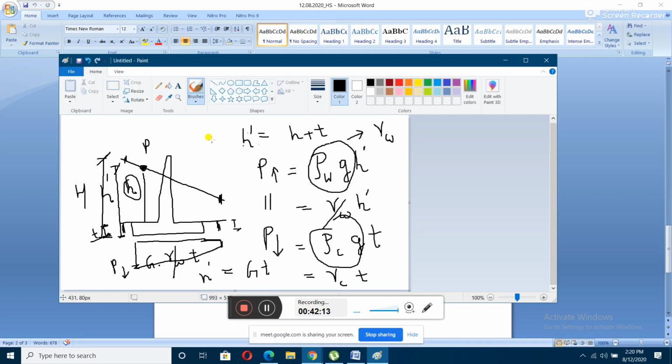So what do you mean by horizontal and vertical creep? There were sheet piles, right? This creep is known as vertical creep, and after that there is flow of water like this, a horizontal flow of water like this. This is known as horizontal creep. So he did not distinguish between this vertical creep and horizontal creep.